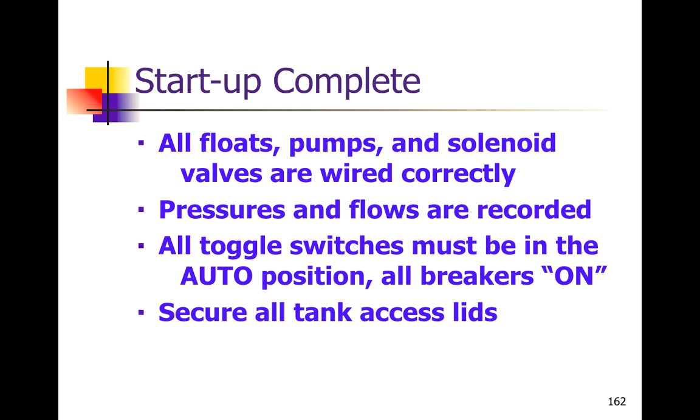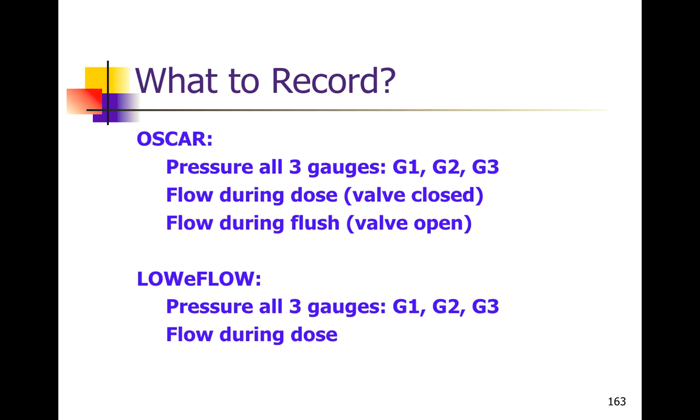The worst thing that can happen, in my mind, at this point, we've done all this great work. The property owner has paid a lot of money to have the system in. We leave the system off, and then they move in. No one remembers to turn the system on, and now we flood the tanks, and we potentially have some other issues. So leave all the toggle switches in the up position, leave all the circuit breakers in the on, and also always remember to secure the tank lids.